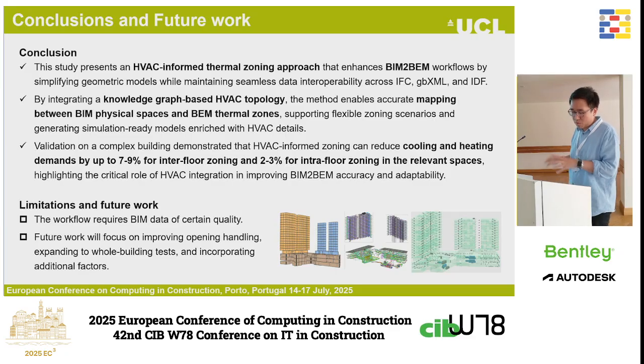The third one is that our workflow was validated on a very complex building, Wemple Street. It is very complex, not only the building geometry, but also the HVAC system. And there are some results. As you can see, the difference is not quite a lot. And we want to highlight the critical role of HVAC integration in improving BIM2BEM accuracy, reliability and flexibility. It's very important to take the HVAC information into account when you want to do thermal zoning for building simulation.